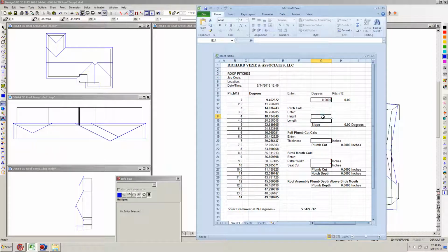And again, it's a 6 tab and then 12. And so my total roof thickness, 5.5 plus 5/8, is 6 1/8 inches, or 6.125. Hit tab. And so now it tells me that my actual plumb depth is 6.8480 inches. Okay? So I can just go ahead and select that, Control C, just so I'll have it in there. Actually, yeah, that'll work for now.